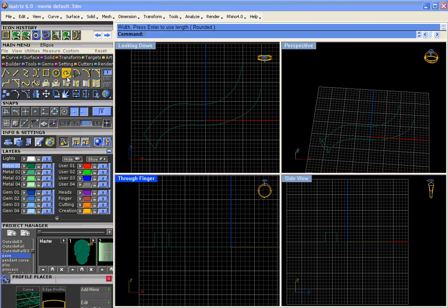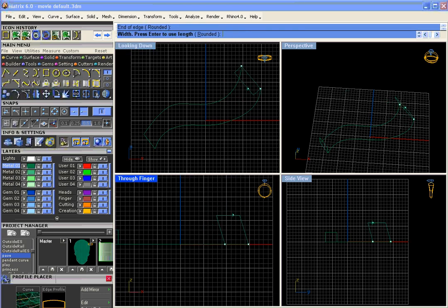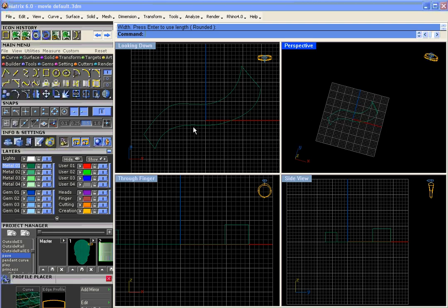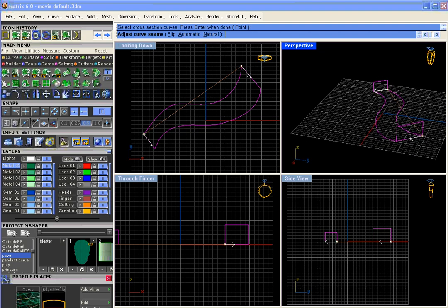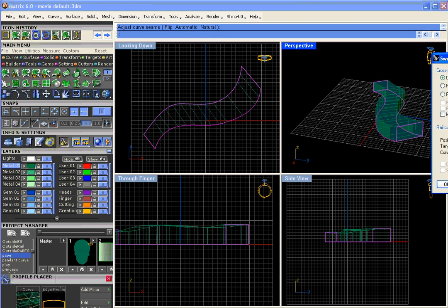Do that again. Rectangle, 3 point, 1 point, 2 point, straight up. Okay, now the point to this is I'm going to use Sweep 2 again, the traditional Sweep 2: first rail, second rail, profile, profile, enter. Make sure the arrows are in the same location, so they're both on this rail curve, and they're pointing the same direction, and press enter.